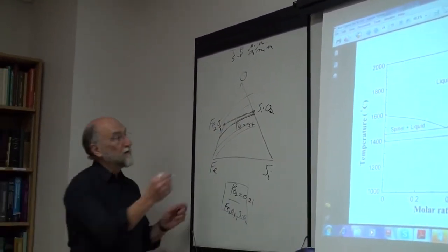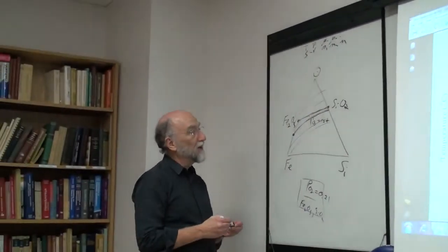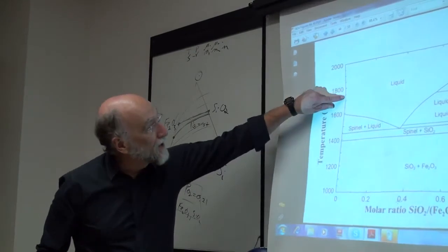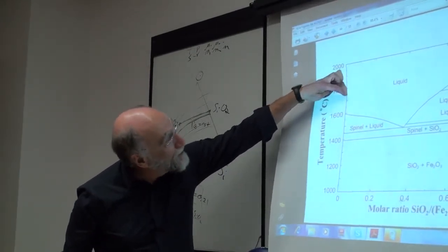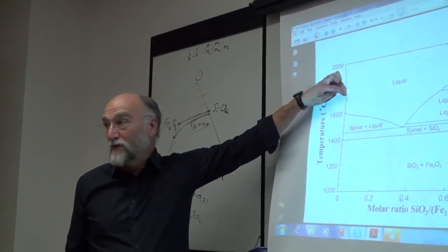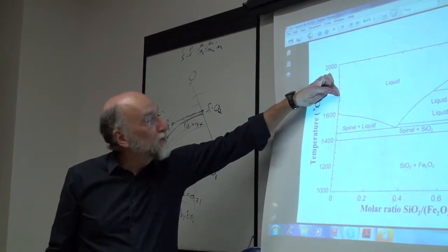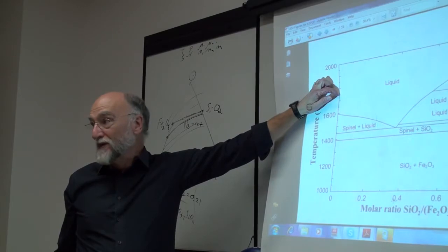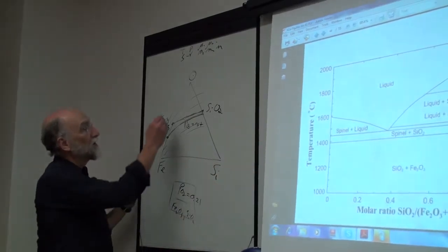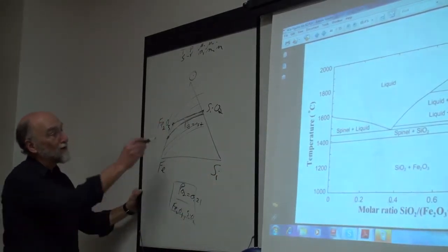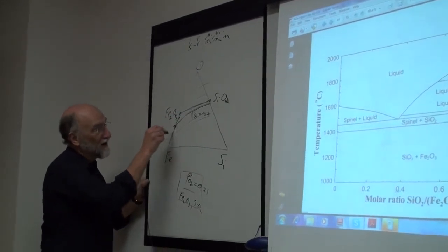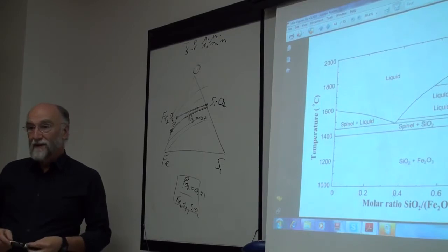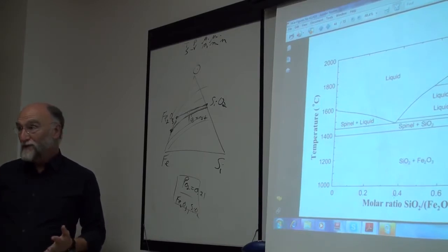Okay. So even when you're over at this end, this end over here is not Fe2O3. The liquid right at this point is not Fe2O3. Okay, the liquid is whatever you get if you started off with Fe2O3 and put it into oxygen at 1 atmosphere. If you're in the liquid region here at 0.21 atmospheres, the liquid is whatever the liquid composition happens to be at 0.21 atmospheres.